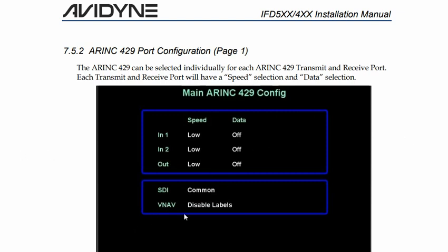And the next piece you'll see down here is VNAV. So part of this GPS 429 output has the capability, if we're talking about a WAAS installation, to provide vertical navigation by way of GPS LPV approaches. So any of your GPS related vertical navigation stuff requires WAAS.